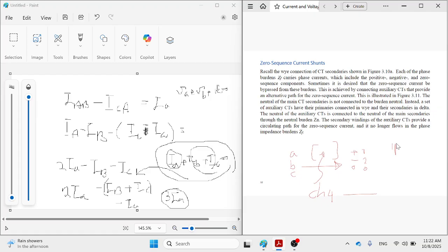Okay, single phase means one phase to ground fault. Okay, single phase fault, two line to each other, two line to ground. Okay, these are unbalanced faults. And we have three phase fault, which is considered as a balanced fault. Okay, so in the case of analyzing a power system, zero sequence appears only in this type of fault, and it is very important to detect the fault in a power system.